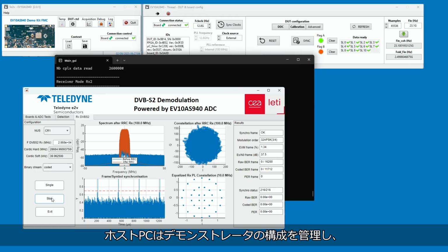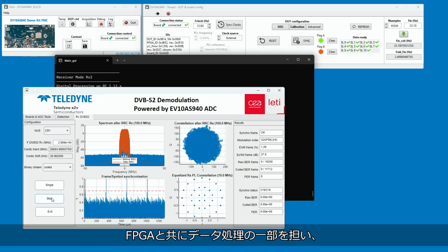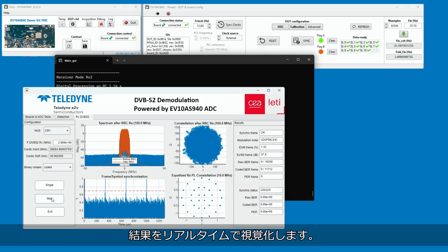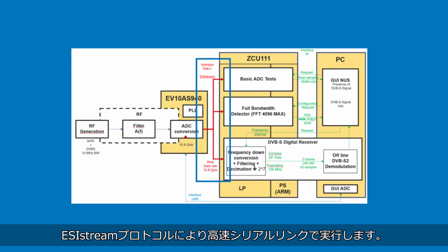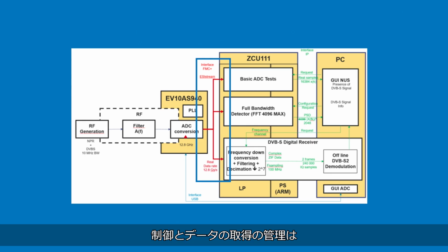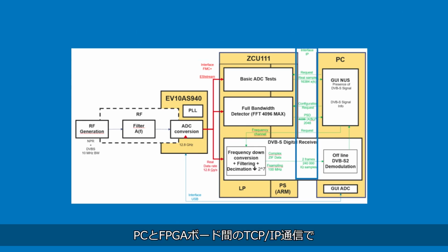The host PC manages the demonstrator's configuration, handles parts of the data processing from the FPGA, and provides real-time visualization of the results. The ADC streams data to the FPGA via high-speed serial links over EasyStream protocol, while control and data retrieval are managed through TCP/IP communication between the PC and the FPGA board.